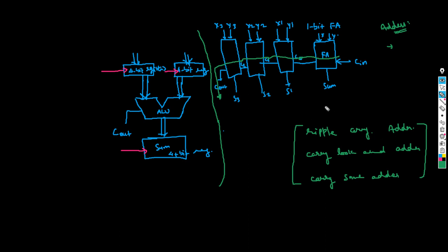So there are different architectures to mitigate your risk. The way you construct 4-bit or 8-bit adders, you should know the time it is going to take, and whether it is going to meet the frequency targets in your design. The reason I'm covering all this is that the moment you start your physical design activities, you will never see them in the form of functionality. That is the biggest problem with PD engineers. At the end of the day, it is register-to-register paths and combo logic, and that is how they always talk.